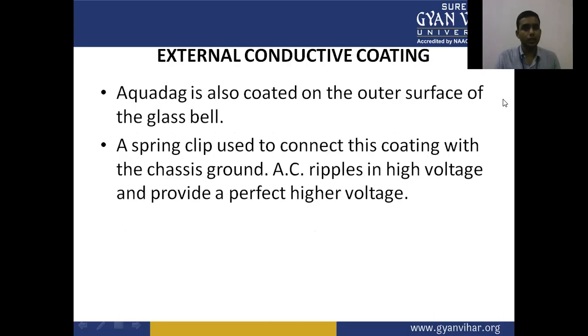External conducting coating. Aquadag is also coated on the outer surface of the glass bell. A spring clip is used to connect this coating to the chassis ground, which removes AC ripples in the high voltage and provides a perfect high voltage.